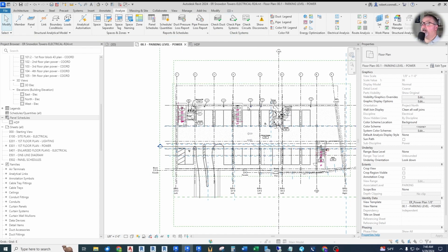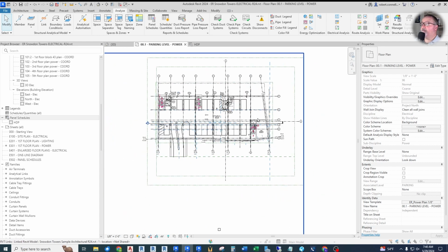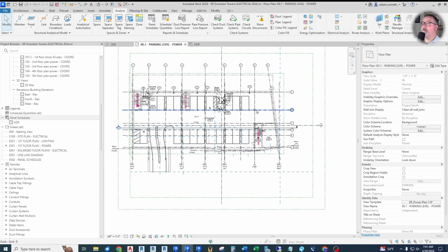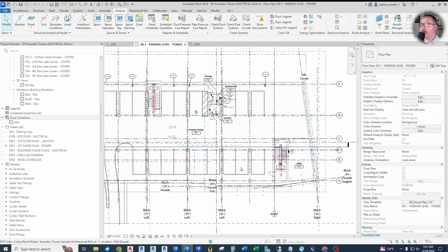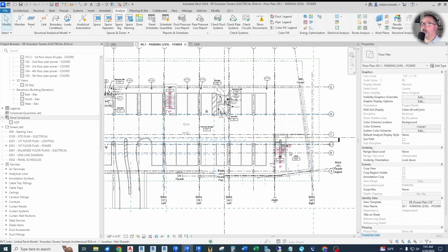Now I'd like to get these chargers connected, and I often will put a separate panel board for the chargers. It leaves a panel board available for future chargers as they want. We can upsize it, and I just like to keep those on their own separate charger. You can also meter those separately if you like.